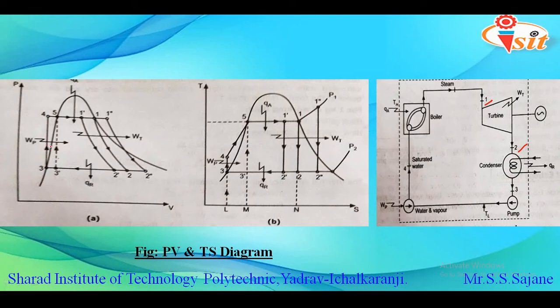Now the next process is indicated by line 4 to 5. As the water enters the boiler, it is first heated up to the saturation temperature or evaporation temperature T1, and during this process the state point moves along the curve 4 to 5, called sensible heating.